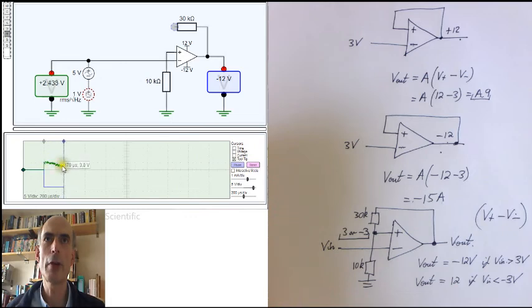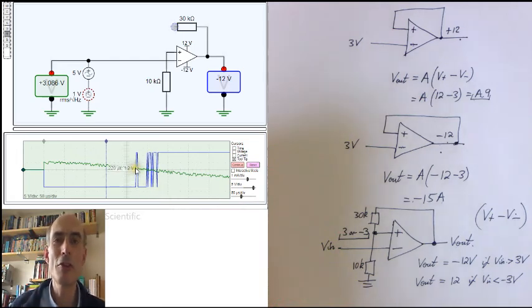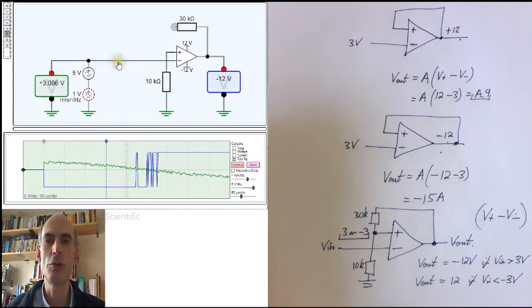You can see we now have a very noisy sine wave. And we now have a rather unpleasant looking digital signal that results. And that's because if we zoom in and have a look at that in a bit more detail, you'll see that the addition of the noise to this sine wave here causes the total voltage here to drop below 0 and then come back above 0 and then drop below 0 and above and below and above and below and above and so on quite a few times, while the sine wave is still just going down.